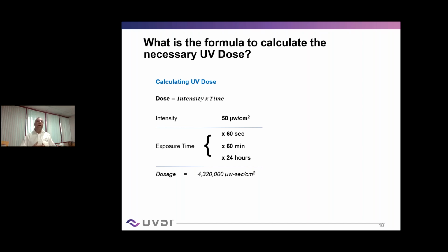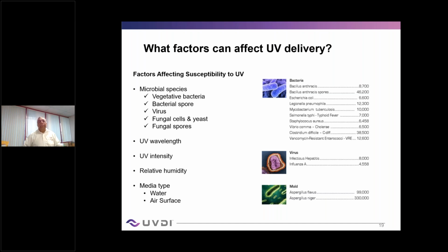So the advantage of accumulative UV is great. You don't really have to worry about which microorganism is there. There is a lot of dose which can be applied. Now, again, this is on the surface. You have to keep in mind that you have fins and you have the depth of the coil. So what you have on the surface is not so much what is inside, but if you size it correctly on the front, then you can actually achieve the amount of dose you need to penetrate and kill everything inside the coil.